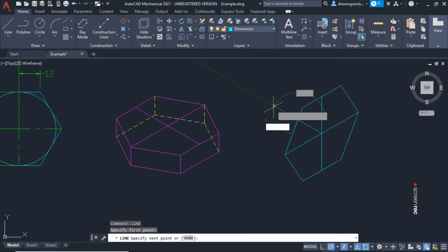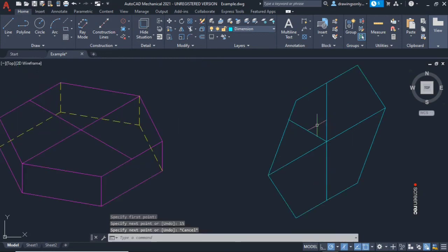Realize that this one is standing. I measure across the center. So if the width of the nut or the thickness of the nut is 10, I would measure across 10 from the center line. So from here, I'm going to copy the points and I'll paste over the hexagon. I'll move it from the center across.